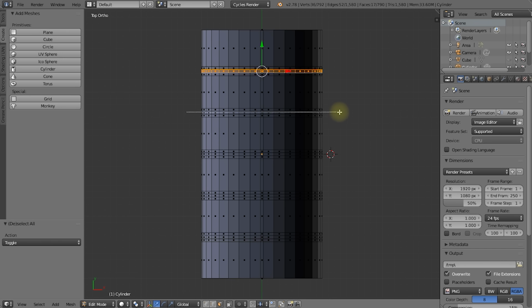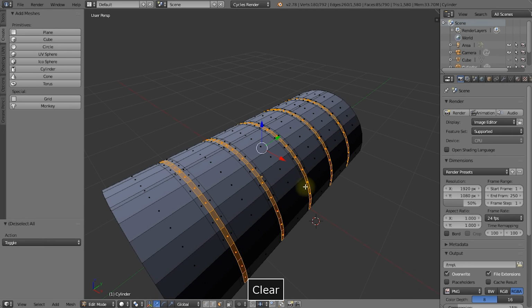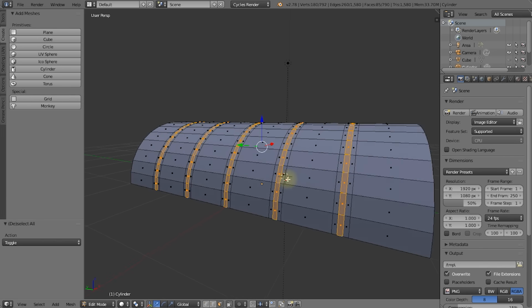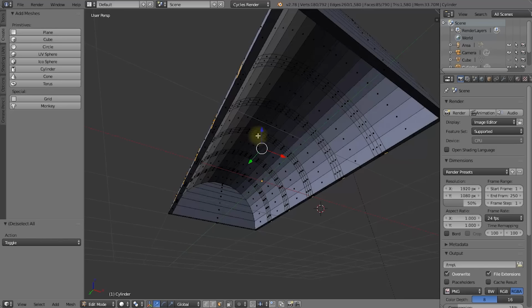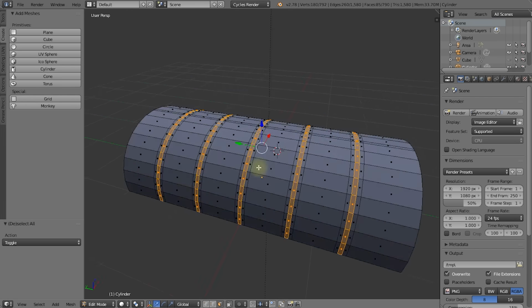So let's click and drag around the next set of faces. Press B again, and let's do that again for the middle. Press B again, and one more time, and B, and let's select the last lot. Cool, that looks all right. Press 5 to return back to perspective mode. So now we've got the faces selected, and because we didn't have wireframe enabled, we only have them selected on the outside, which is kind of what I want.